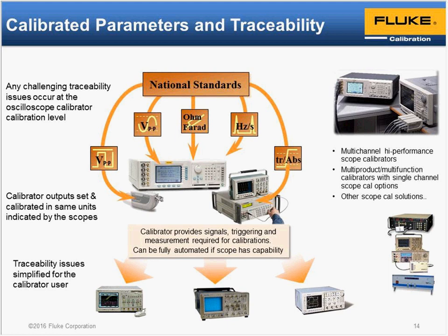And on here, I'm portraying the role that the oscilloscope calibrator provides as a link between national standards and the unit under test oscilloscopes that we're calibrating, so that we can provide this unbroken chain of traceability from those standards to the test equipment and, of course, on to whatever tests they are performing. And that's a very key link, because in calibrating the oscilloscopes we need a variety of different parameters, and some of the key parameters I've depicted there: peak-to-peak voltages, frequency and time, rise time, resistance and capacitance, a whole variety.